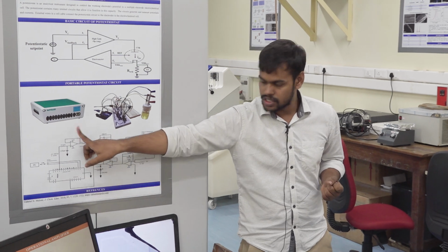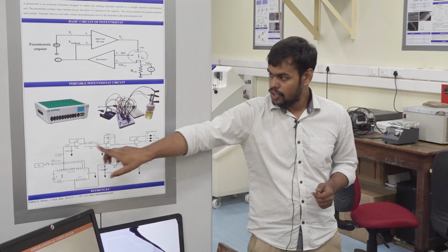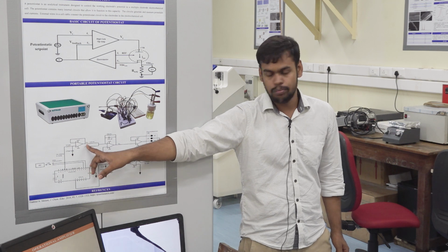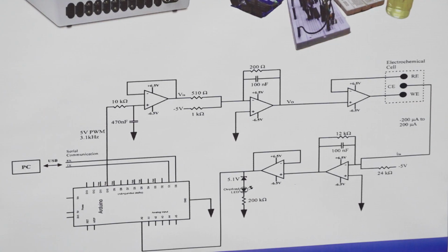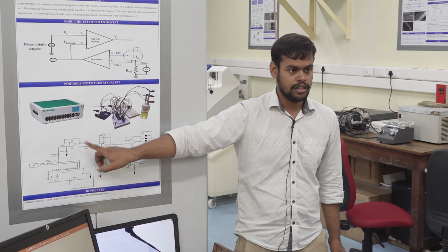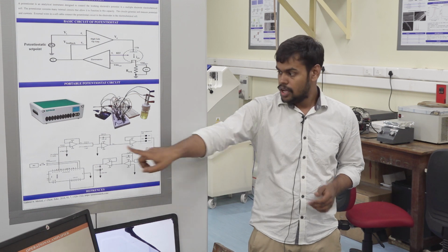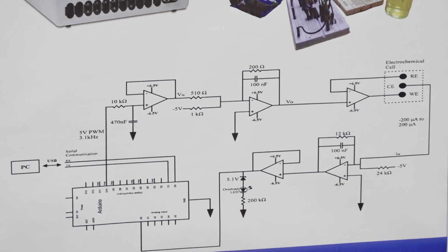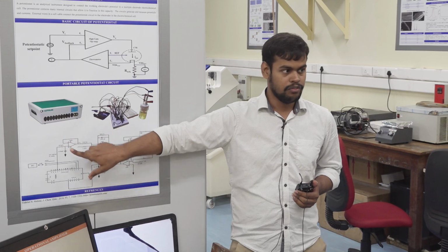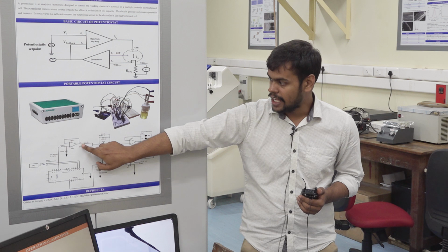Now you see, this circuit that you are seeing is actually called the follower amplifier. What happens in the follower amplifier is, when you short the inverting input to the output of an operational amplifier, whatever is the input will be the output, it will come as V in. Now, this part is a summing amplifier part. It's a follower amplifier. Whatever is the input will be directly the output of it. Now, we have the output. What we want to do is, V in is there.